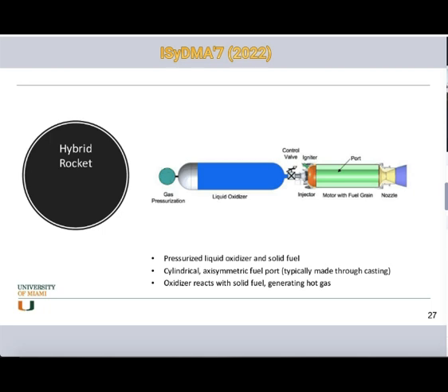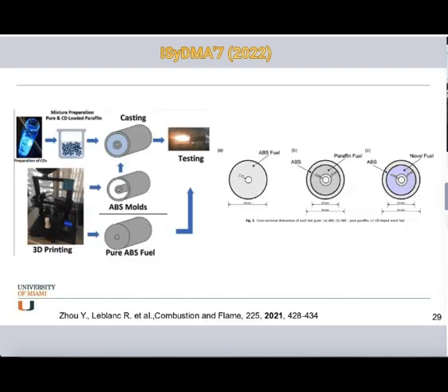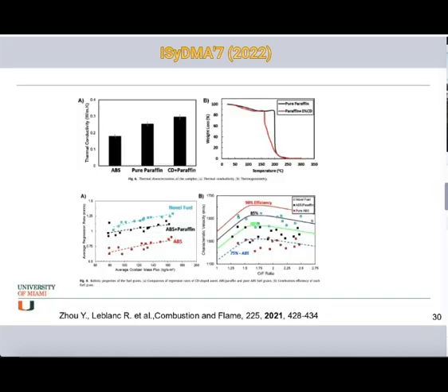Yeah, so if I look now at the results, we can go to this figure. We can see that if we look at this thermal conductivity, we have the polymer ABS and paraffin compared to carbon dust and paraffin. So this thermal conductivity will have a 20% increase. Figure B is related to TGA, thermogravimetric analysis, and we can see again that with the carbon dust in the system, the paraffin with 1% has been improved in terms of conductivity.